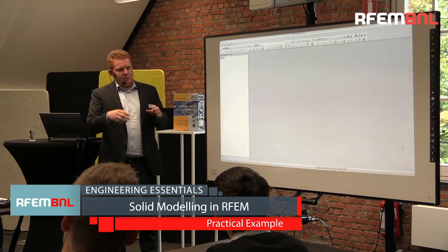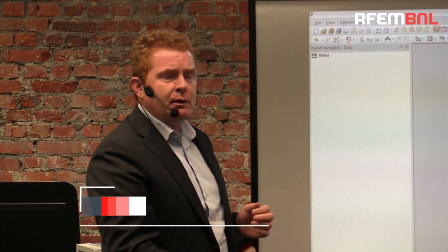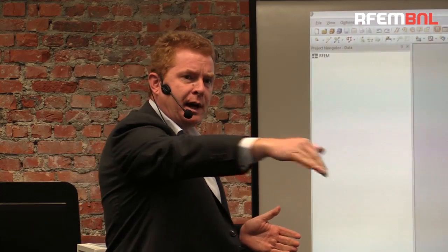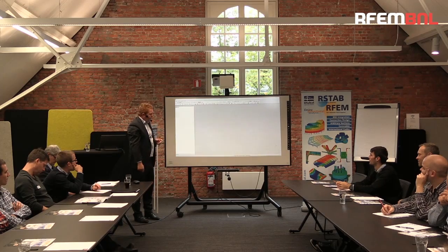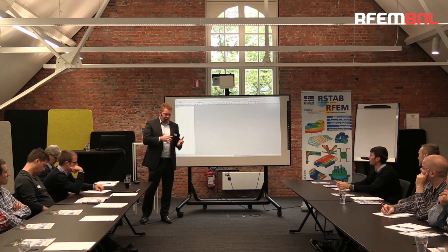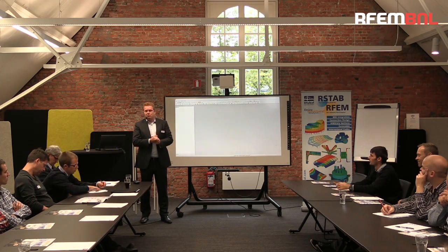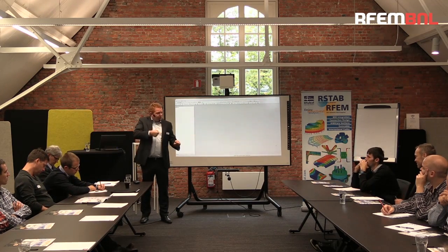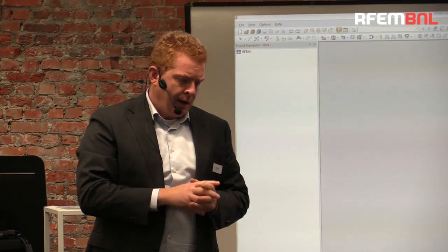But imagine that you have a construction site. You take out some ground. You have some sheet piling. There's always a set of anchors to prevent the collapse of the sheet piling, that sort of stuff. And Jo showed it already on the picture. But imagine that you have some pre-stressed strands, and it's connected to a mortar block or something, and then you stress it, and you have to distribute the pre-stressing load to the sheet piling. And this